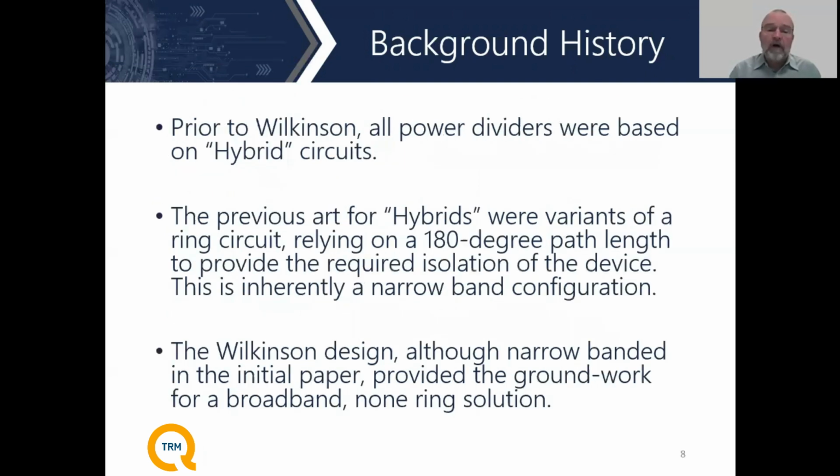Yeah, so immediately prior to 1960, like I mentioned in the introduction, all power dividers were based on what they called hybrid circuits. And these are all basically rat race ring hybrids, where in order for these to function, you have to rely on a delay line to make the cancellation. Delay line has phase dispersion associated with it, and therefore its effective frequency range for having that phase cancellation is very narrow banded. And it really works quite well. And don't get me wrong, it's a wonderful circuit, but it is limited as far as bandwidth is concerned.